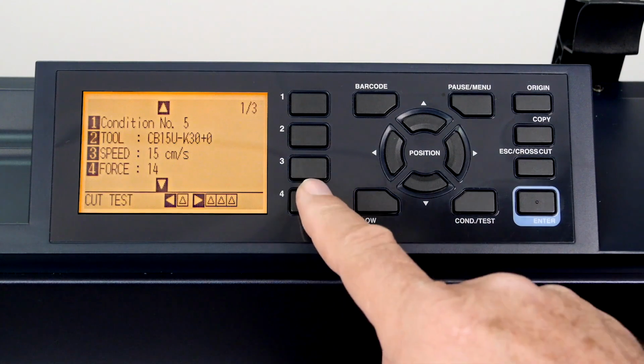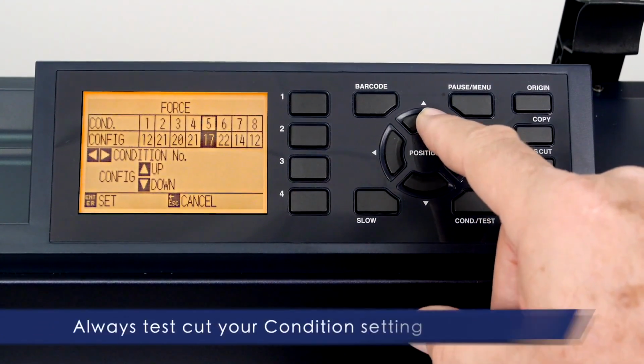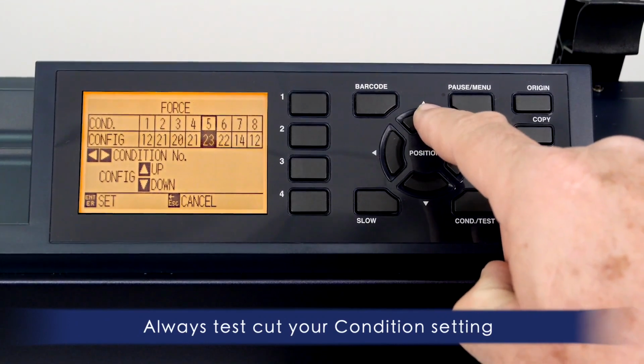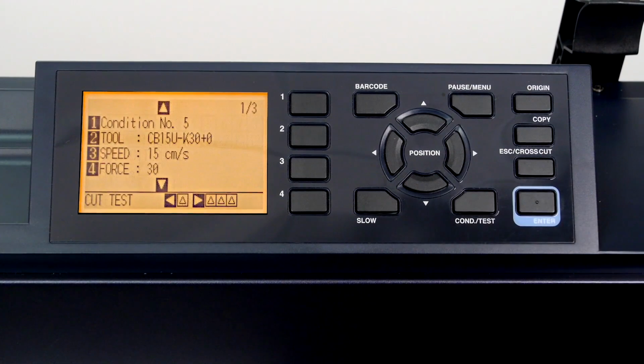Next, we can set the force to around 30. Keep in mind that we have tested this value for this type of media, but you may find that you'll end up using a different value. Then press Enter. Next, we will enable tangential mode by pressing the down arrow key until this page appears.